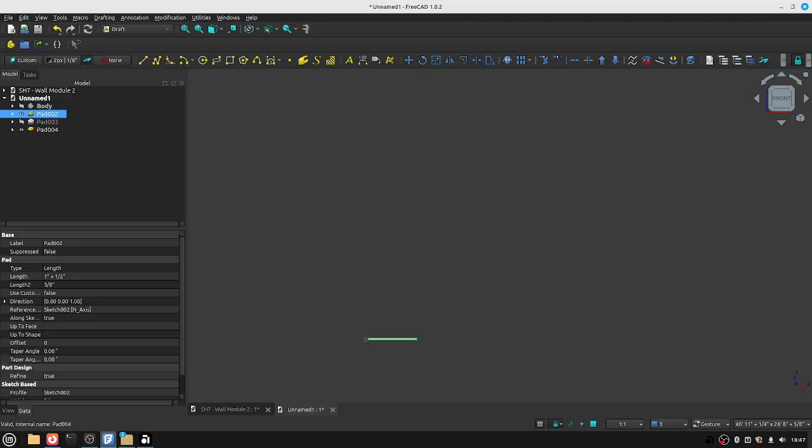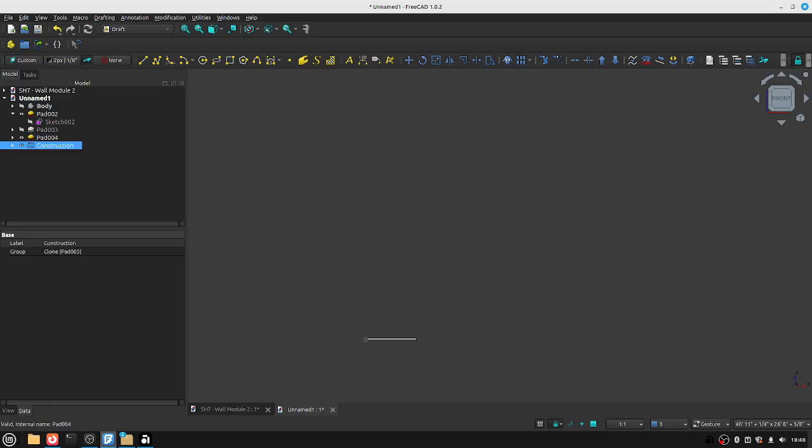So you got to clone it. You got to turn it into a dumb object. Unless the pad, the object itself might actually be within. No? It's got the sketch and the pad in one. You cannot move those things together because the underlying sketch doesn't like moving. So you got to just take this thing and make a clone of it. That gets rid of all the detail. It turns it into a dumb object. So if you clone it using this feature, it says